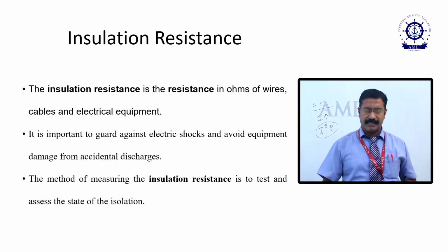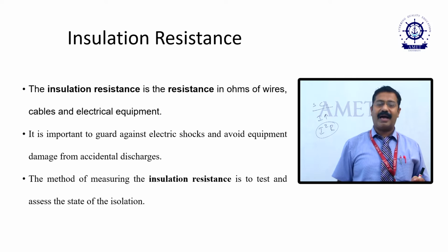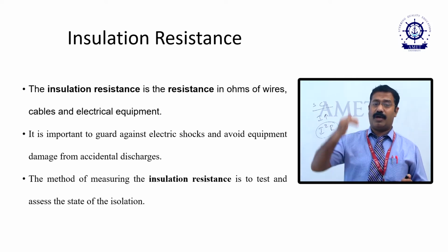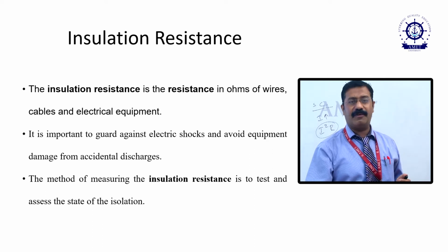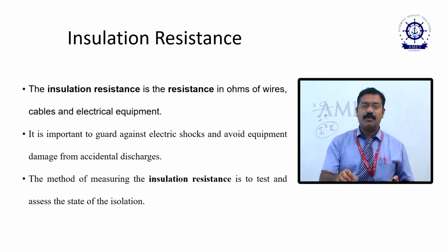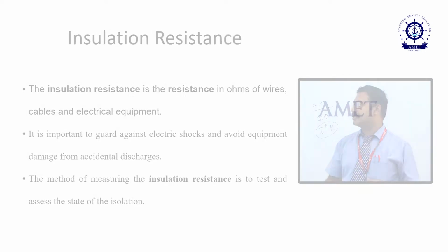If that is the case, if I take this motor on my ship, then I am believing that for the entire 6 months, 1 year or 1.5 years, this machine will work. Therefore, I have to check whether it is in good condition. For that, I need to measure the insulation resistance.